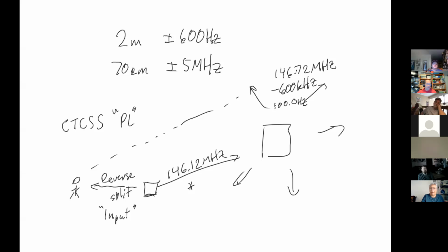If the repeater user says your transmissions are breaking up, that means you're too loud. On this radio, you don't have a microphone gain control at all. What it means is you basically move the microphone further from your face, and that reduces the amount of signal going in.